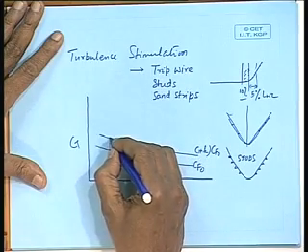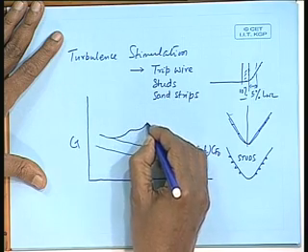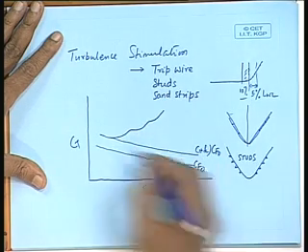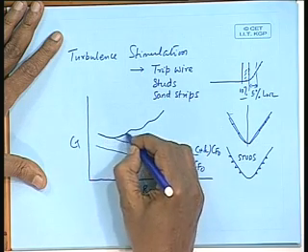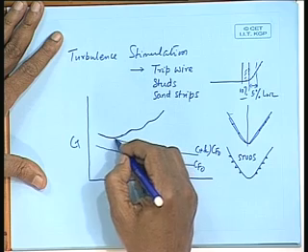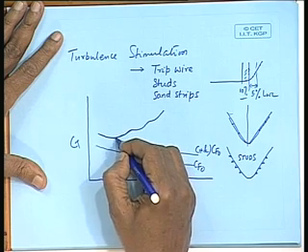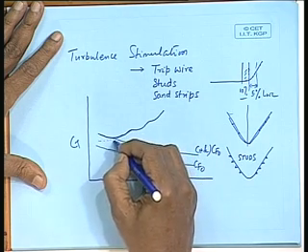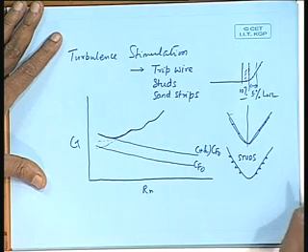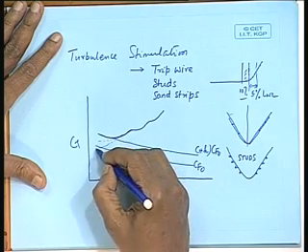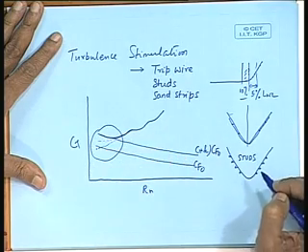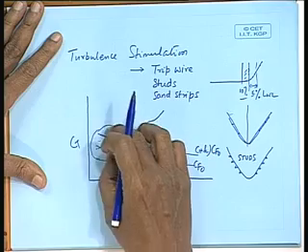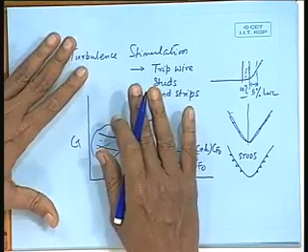Now, here we have seen that the resistance curve should have been like this, that is at low speeds it should follow this line when there is no CR, and then it goes like this. It may so happen you will find that the resistance curve is actually going like this, or even coming down to this line, even going below the CF at low speeds. Then you know something is wrong here, and the reason for this will be laminar flow.